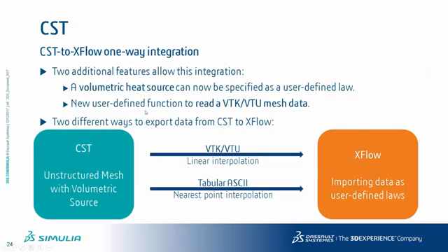Okay, let's jump to the second tool that we couple with XFlow, and that is Dassault Systèmes SIMULIA CST Solver. What we basically do is take the electromagnetic simulation of CST, calculate the heat sources that it produces, and then import that into XFlow. Now, compared to the previous integration, that's more of a one-way coupling. So we read the results from CST into XFlow, but we do not exchange anything back to CST. That's why the arrows are going one way.